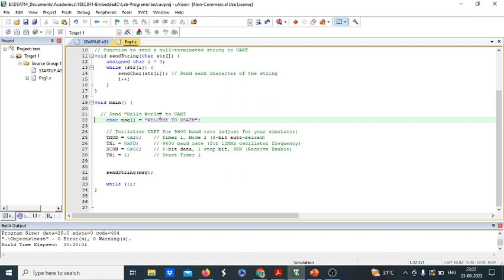Just to brief on what is required for a UART: an understanding of the serial communication, then we need to know the SMOD register, then a little bit of the TMOD register, the timer, that is TH1, and to start the timer. The SBUF register is mainly used to hold the data whenever there is a transmission or reception happening, and then the logic of the program.